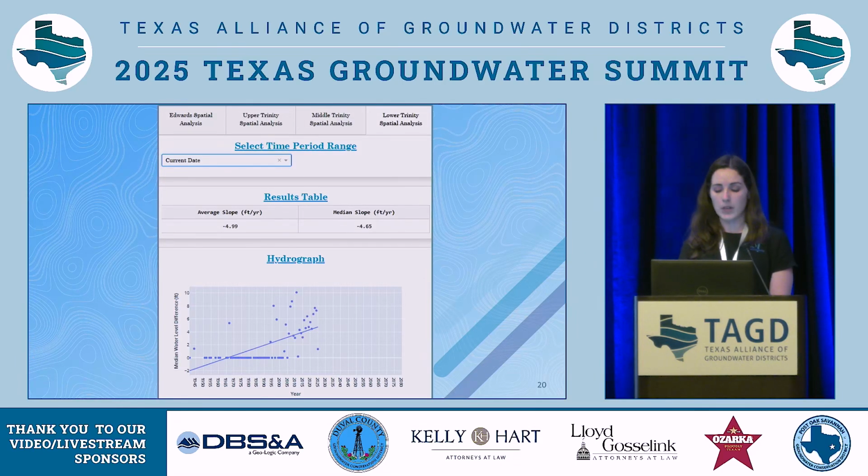This hydrograph shows the median water level difference of water levels over time. This is the middle value of water level change for a particular year. Displaying it this way prevents the values from being skewed by extreme highs and lows, and it shows the typical rise or fall of water levels over time.